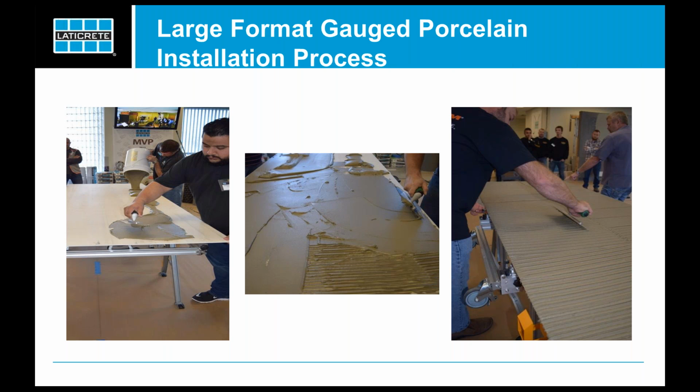All right, so we've selected our adhesive mortar. We're ready to go now as far as installing these materials. If you take a look again at the staging area, you see the adhesive is mixed a little looser than traditional adhesive mortar. The reason for that is, again, you want to make sure that the ridges collapse onto themselves so that you don't get any entrapped air. So you pour out the adhesive mortar on the back of the panel, and you start using those required trowels, and you'll see that the ridges are always going in one direction.